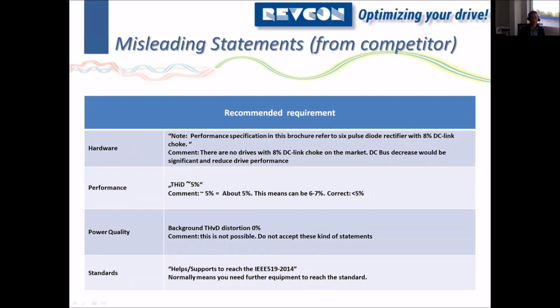Has any one of you ever seen a drive with a DC link choke of 8%? Please raise your hand. I would be really interested to hear about this special drive, but I've never seen any drive with 8% DC link choke on the market. And actually it couldn't be possible, because the DC voltage drop inside the drive would be so huge they would not be able to give the performance they need. So quite a stupid performance specification from one of our competitors.